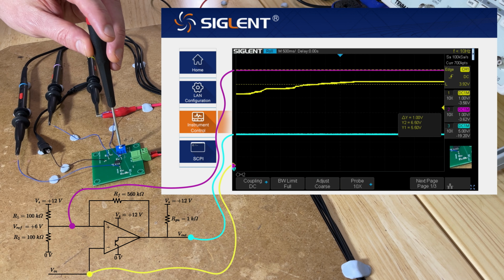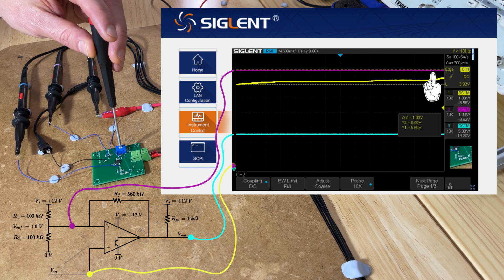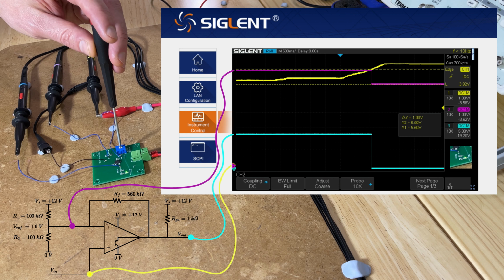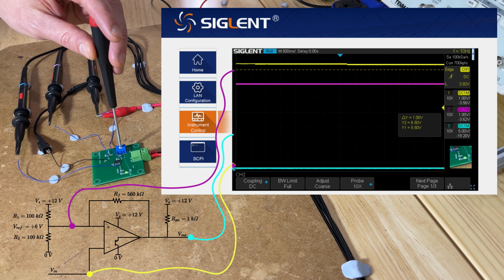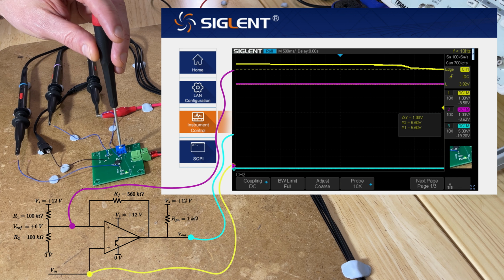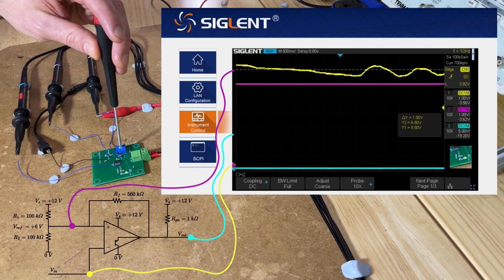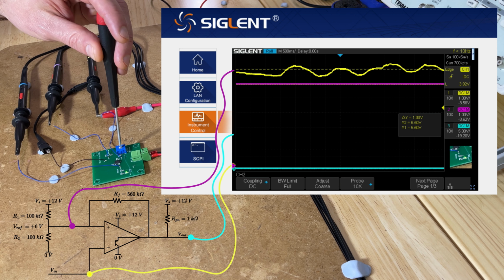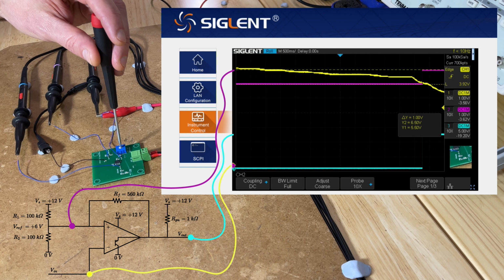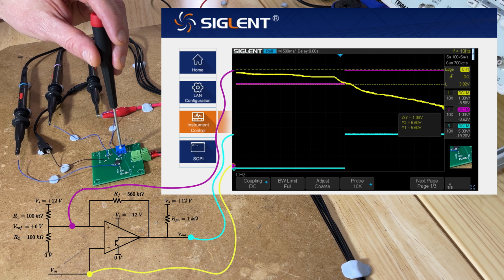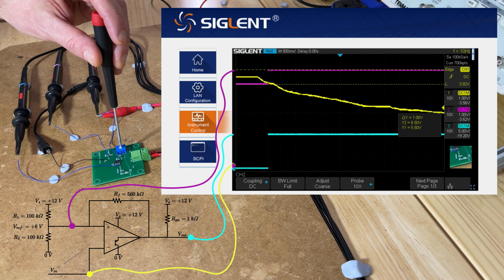But when I cross my reference voltage on the upper hysteresis band, you can see now that the output switches low, and you can see that the LEDs come on, which is good. And then I can slowly lower back down, and I can even go above and beyond that upper hysteresis band. Nothing happens until my input comes down and crosses the lower hysteresis band of 5.5 volts, where we switch back to logic high, and you can see that the LEDs come off.